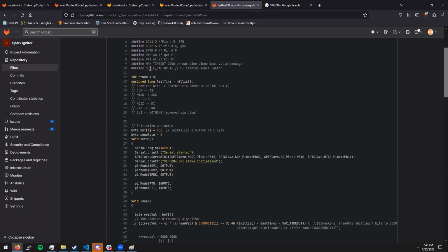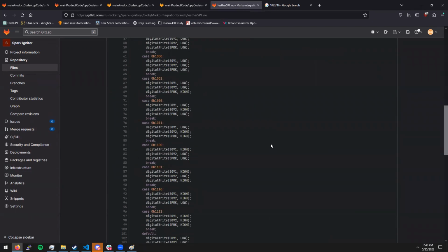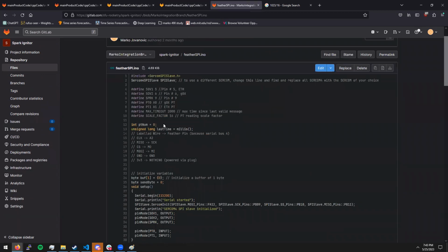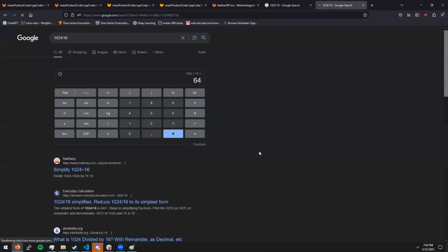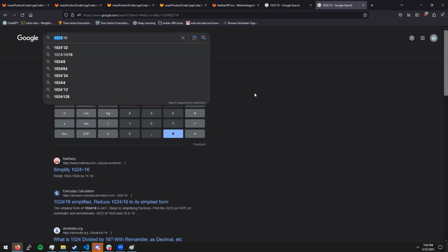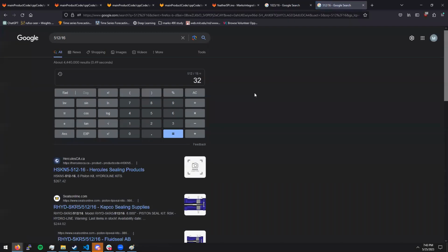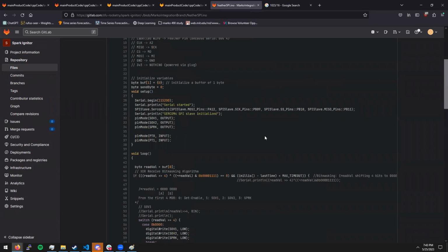So all I did was, instead of 0 to 1023, I wanted it to be 0 to 64. So I just divided whatever value we got by 16, because 1024 divided by 16 is 64. If it was directly in the middle at 512, we'd get 32 as our scaled output. So that's all that's doing.